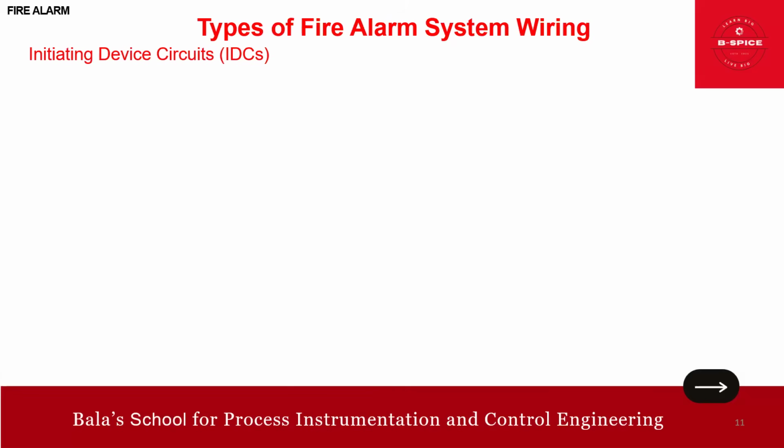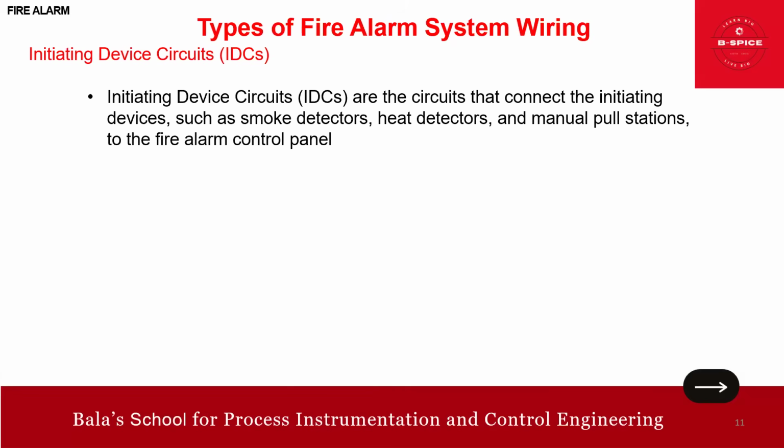Now we have one circuit called the initiating device circuit. We call it IDC. Initiating device circuits, IDC, are the circuits that connect the initiating devices, such as smoke detectors, heat detectors, and manual pull stations, to the fire alarm control panel. So this is the initiating device circuit.